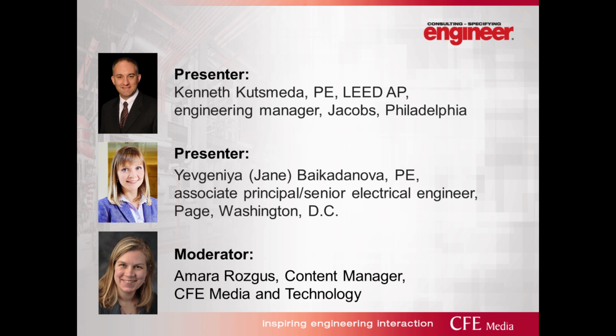All right, got it. Jane, next question is for you. When is an ATS required to be service entrance rated? The service entrance rated ATS is required when the entire load of the building requires to be on standby emergency power. That's when we would specify the service entrance rated ATS.